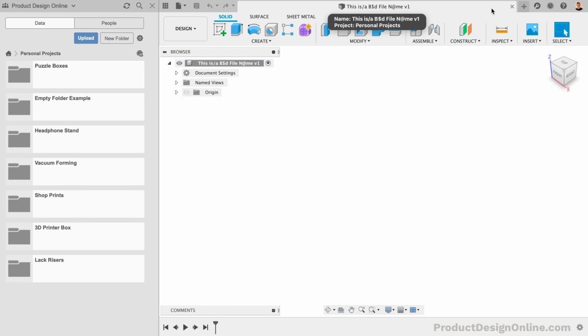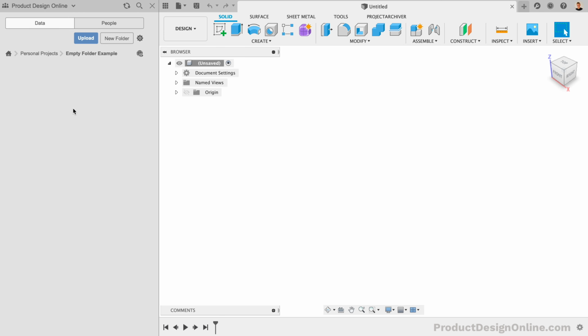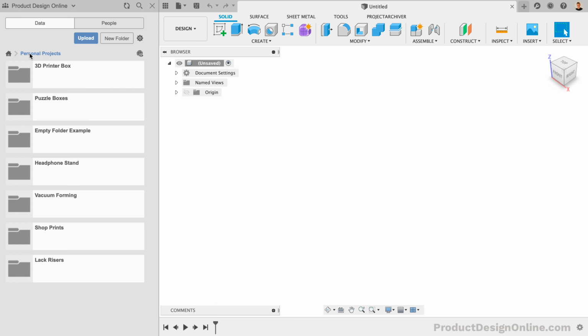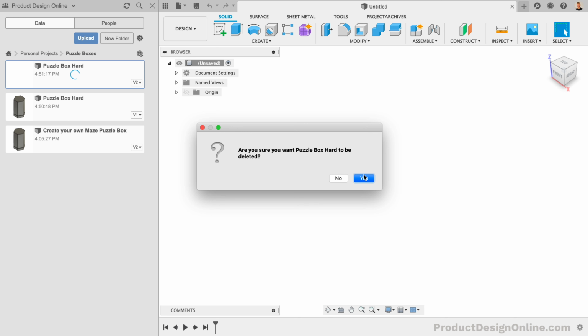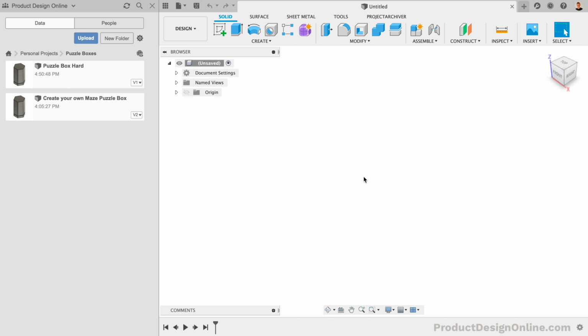Second, if you have any empty files or even empty folders within a project, then it's going to cause an error as it cannot successfully export something that does not exist. I recommend taking a minute or 2 to browse your project beforehand and delete any empty files or folders, and change any file names if you need to, and you'll have greater success in exporting every file in one pass.